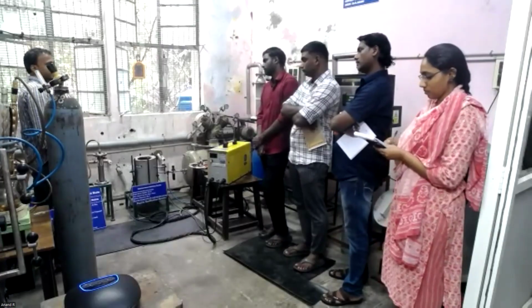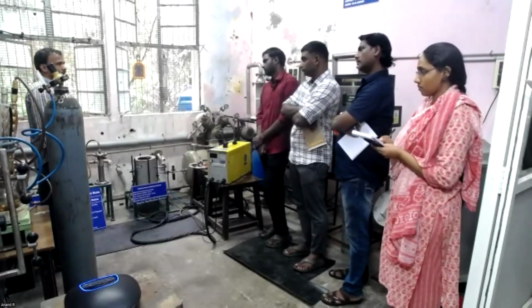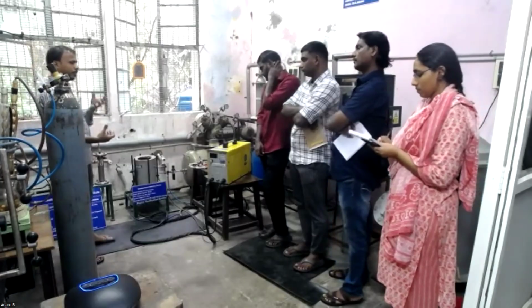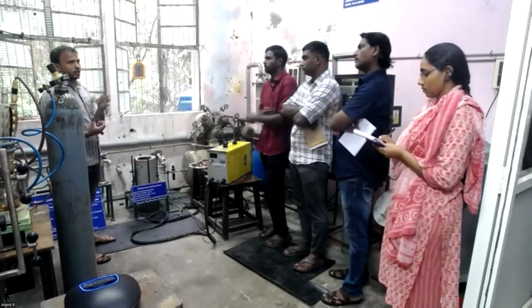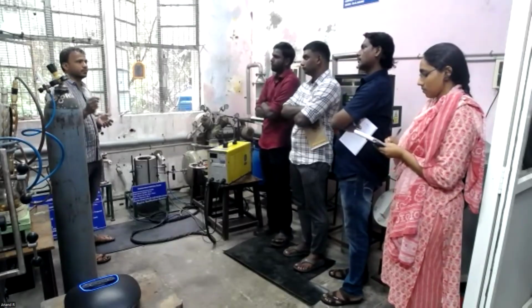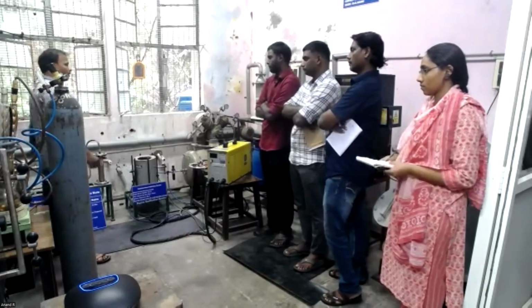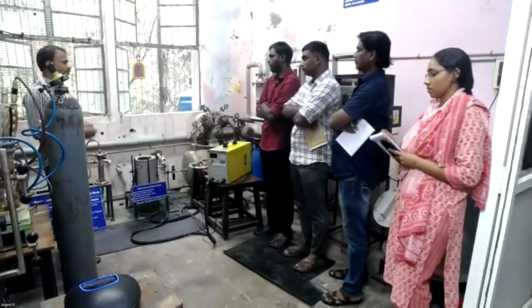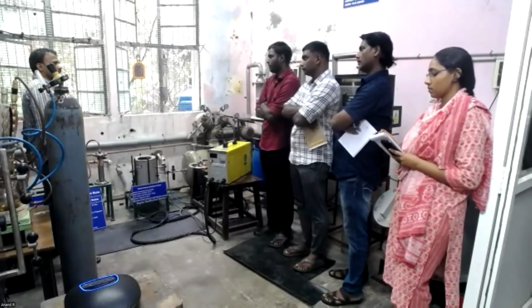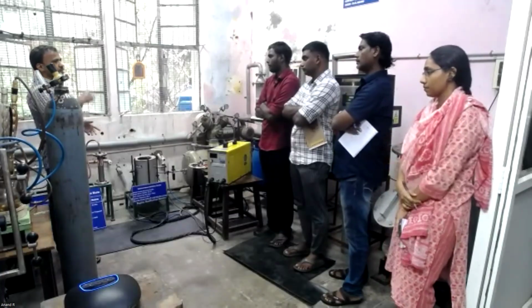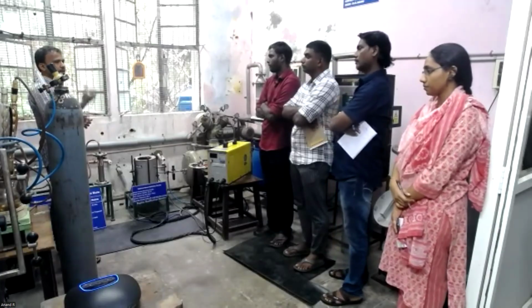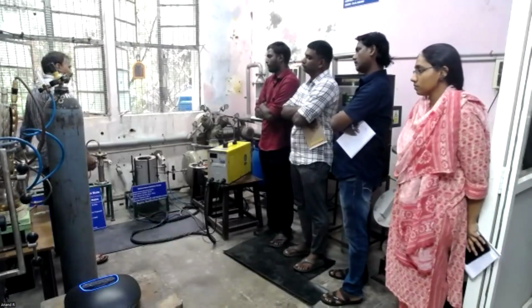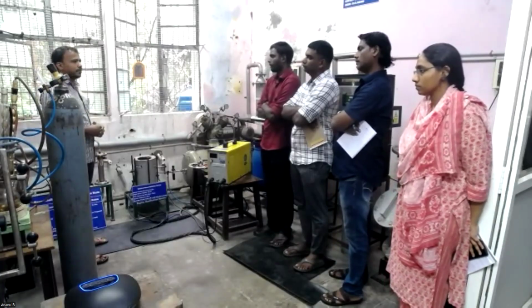Why are we using a mist eliminator? After scrubbing, this is direct scrubbing, so water is directly meeting the syngas. If water meets it directly, the syngas may capture moisture or carry some quantity of water. That water will affect the calorific value of the syngas, so we could not utilize it for further application. So we are using a mist eliminator. It has a porous structure, like a jet pack. It will condense the water present in the syngas, the water will drain down, and then we can get a clean syngas. That may be a combustible fluid.